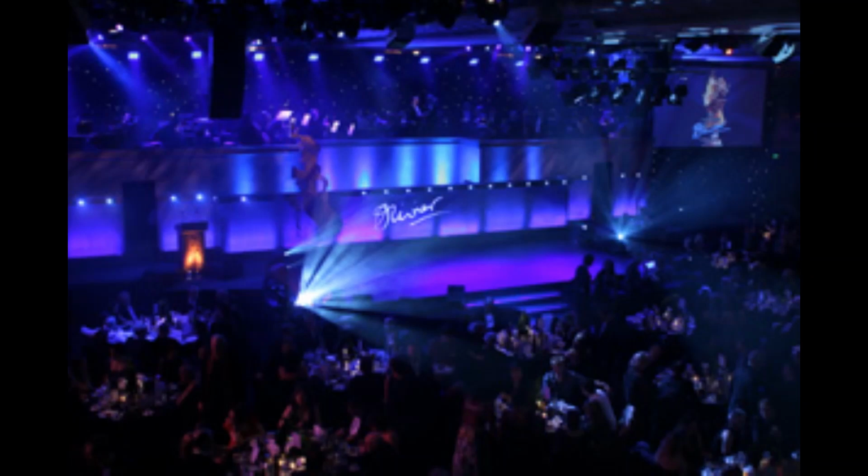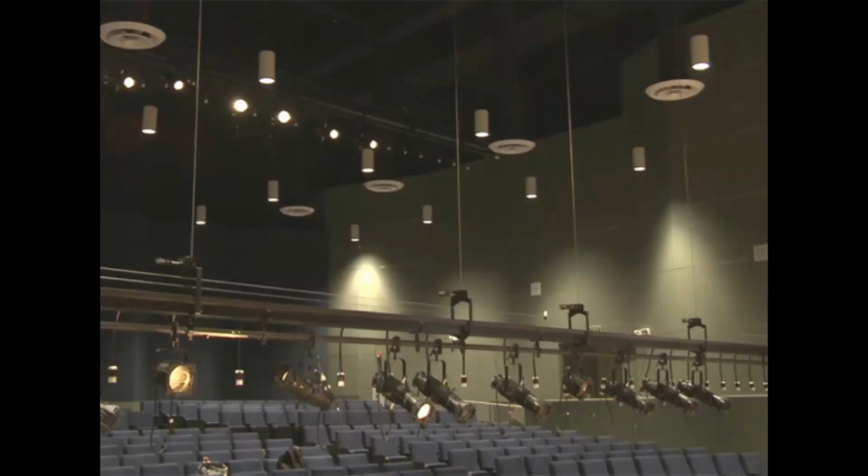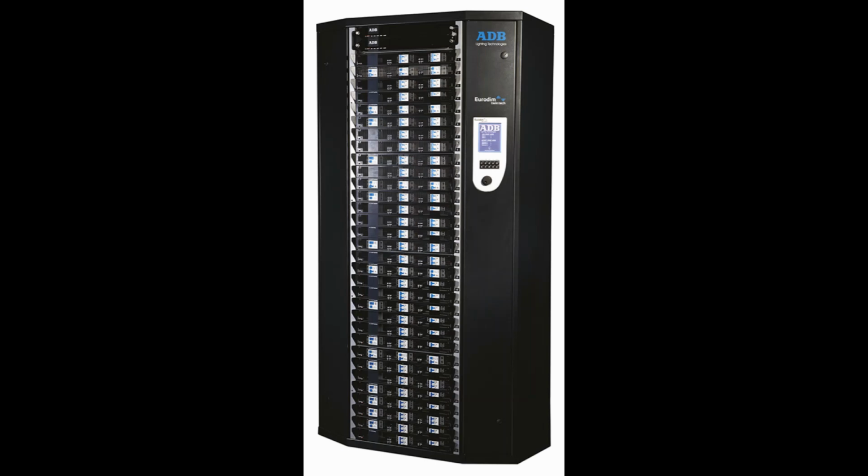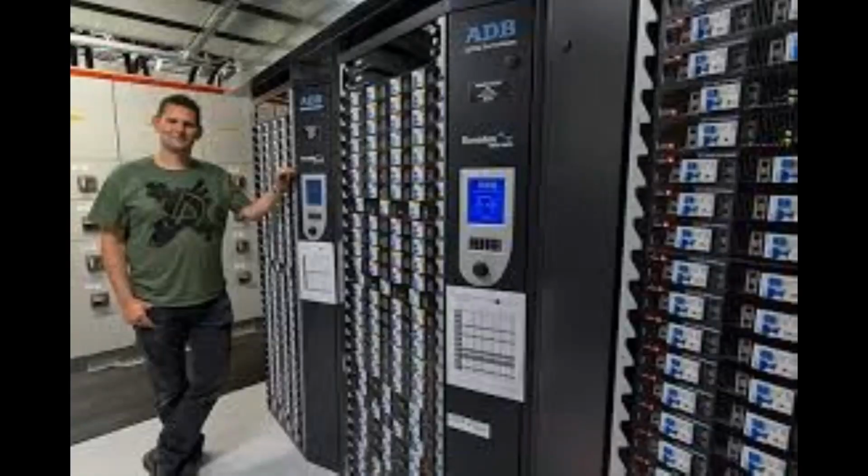There are also usually catwalks or an added electric batten as a front of house of the stage. This is also fitted with a raceway of circuits so that the fixtures can be hung and powered to supply light directly toward the front of the stage. These circuits are often numbered, and each circuit is connected to the same numbered dimmer in a dimmer rack located in a closet or room where the outside electrical power is connected.